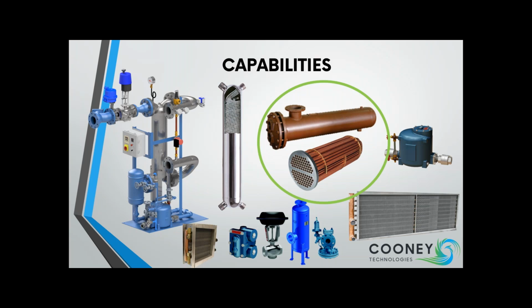Horizontal design, steam to hot water, heat transfer. You'll see the steam bundle with the tube sheet. Usually you have steam in the shell, water in the tubes. This is showing a 2-pass shell and tube heat exchanger. These are pretty common and they've been around forever.